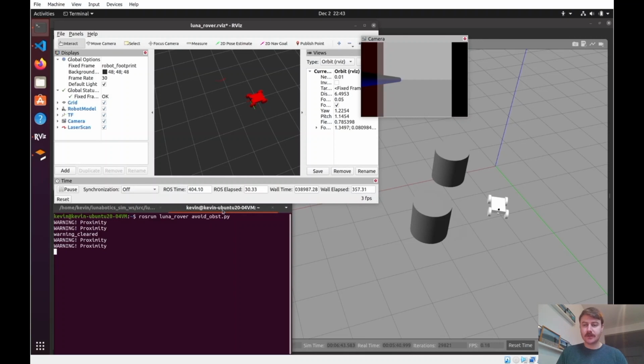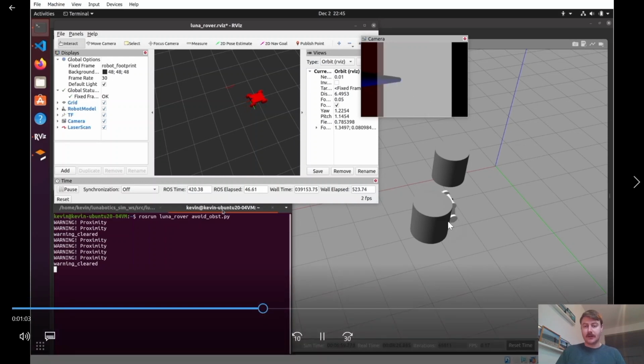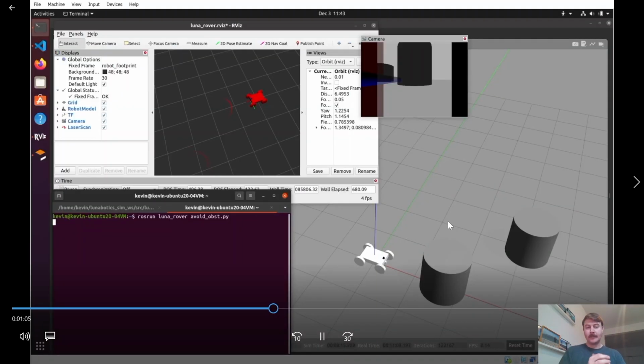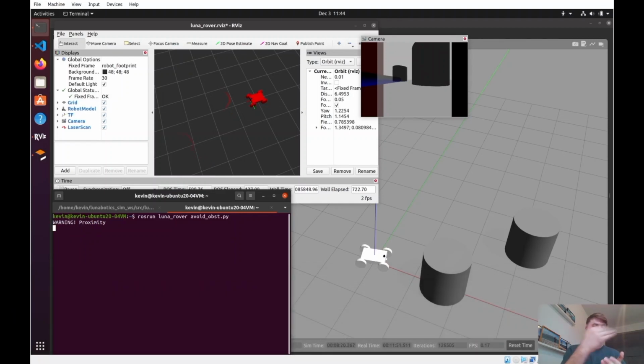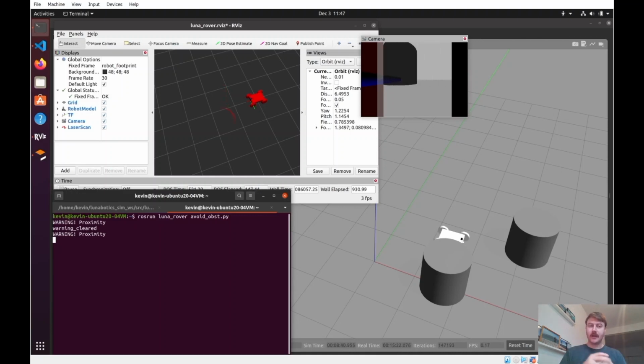needed. So because of that, there were actually some message passing issues as well. What happened was that the latency was so bad that it would drop messages. And so that's what's happening here, is the calculated time based off of what should actually be passed as messages to the rover, messages were being dropped. I had to average out the number of dropped messages so I could control it to a reasonable precision. And so that's why even though it should have been able to be precise, it wasn't. It was only kind of based off of that average, and there was no real way to control the number of messages that were dropped.